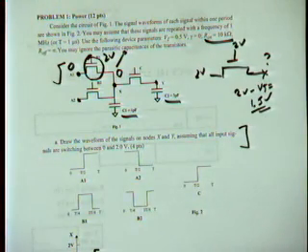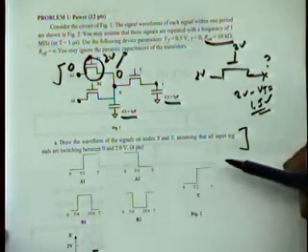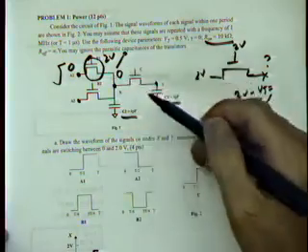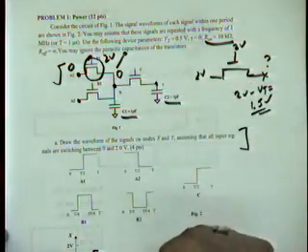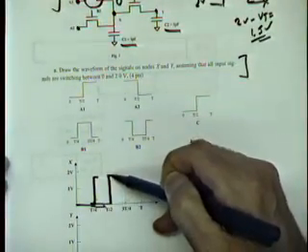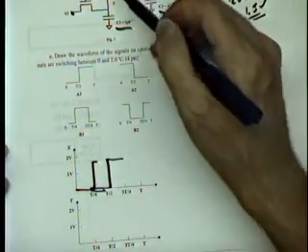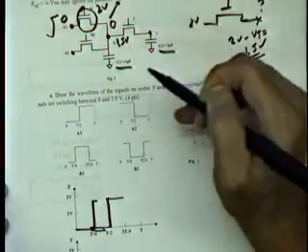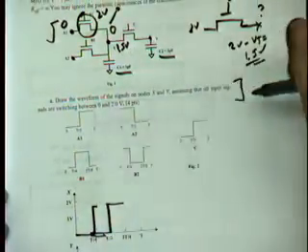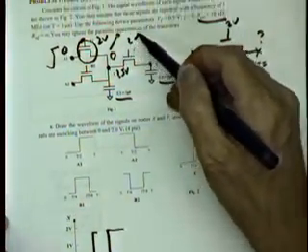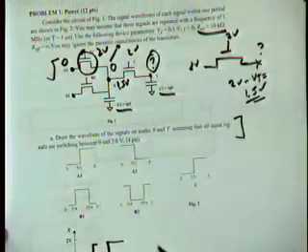That's really what this question was a little bit after, looking at the impact of those threshold losses. Because then, for instance, when I turn on node C, oh, sorry, that's at time T/2. When I turn on C, this is going to go like this, it goes up here, X is going to stay like that. So if you look at the Y output, this is now going to 1.5 volts. C at time T/2 goes also on to 2 volts. So what's the value I'm going to get here? Am I going to get another threshold loss?